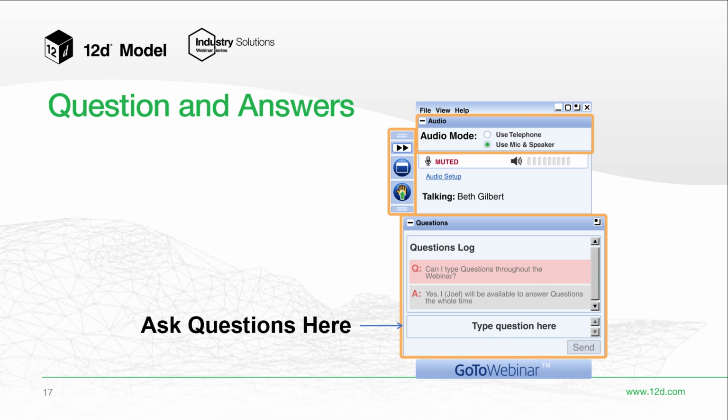Thank you. Yeah, and we'll just do one more live. So Aaron has said, we were told on earlier 12D courses to always copy snippets to the working folder rather than using them from the library. Is this still advised? And if so, is there an automated way to do this? Yes, it is still advised because we will continue to improve those snippets. If you're using a snippet that was created a year ago, it may have, for example in the subgrade functions, new things that might not work exactly the same.